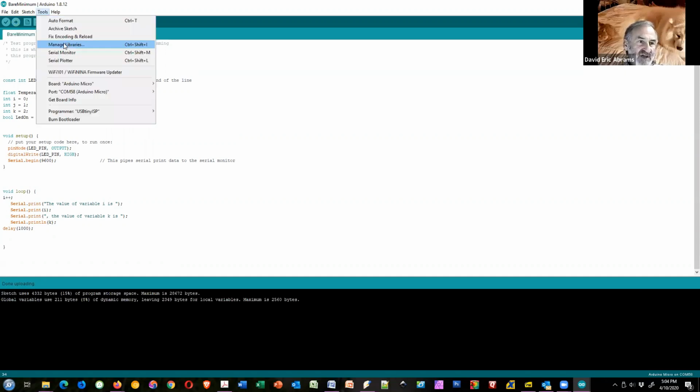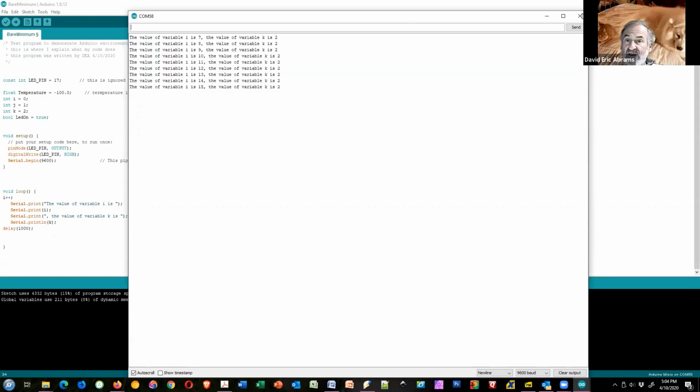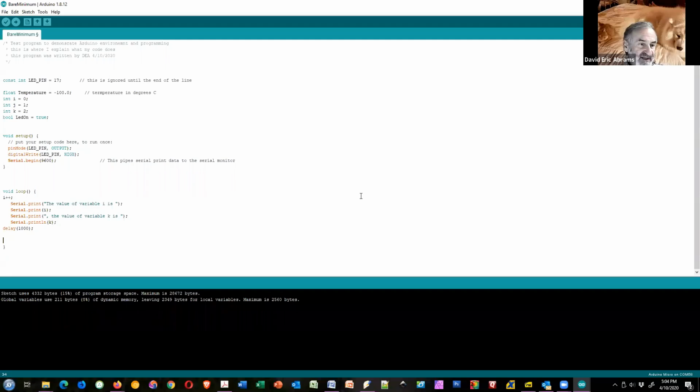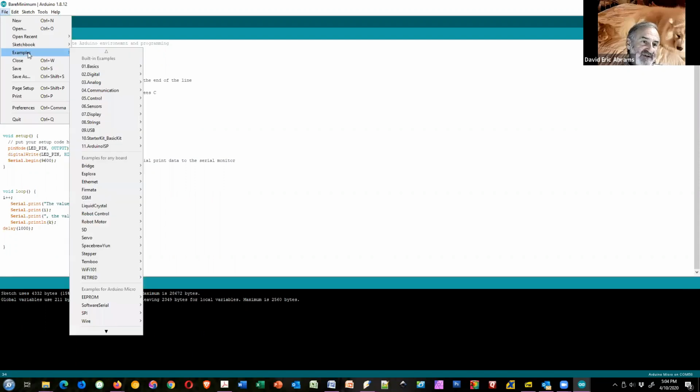All right, so that is my introduction to programming. Questions? Now, what I would suggest you do is hook up your Arduino to your PC, get the environment set up, and then over here under File, there is something called Examples. There's a bunch of built-in examples. The first one you want to try is Blink, because that works with no extra hardware.